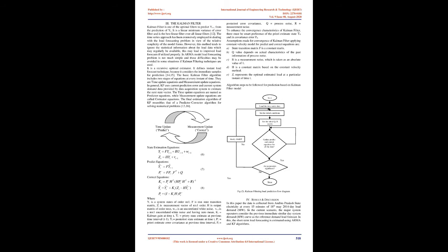When moving average is combined with an autoregressive process, the current value of the time series Yt is expressed linearly in terms of the current and previous Q values of the white noise series Et, Et-1, Et-2, ..., Et-Q. The noise series is collected from forecast errors or residuals when load observations are made.